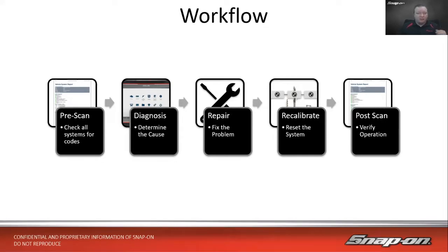Then after that, once we've gotten the pre-scan and shared the results with the customer and gotten approval from the customer, then we would go through our diagnosis phase, right? So we're going to go through and determine the cause, and that in and of itself is a whole other workflow in there. Then after that, we'll repair whatever we come to as a conclusion. We'll go in and fix the problem. Then once the problem is fixed, we'll go in and double check, are there any resets, relearns, recalibrations that need to be done on the system?